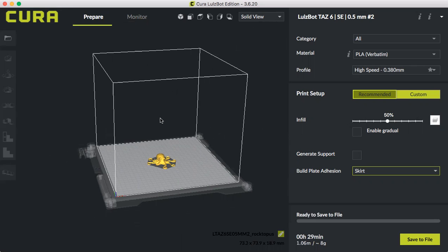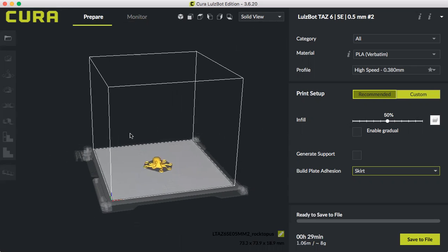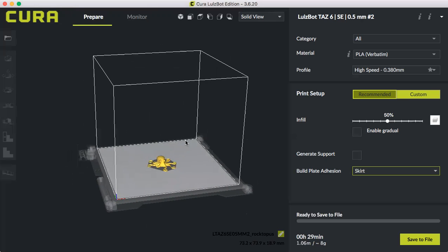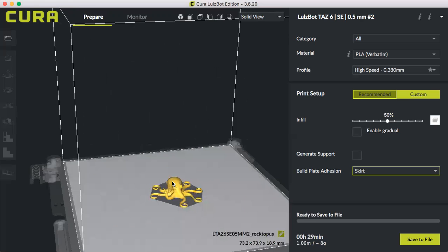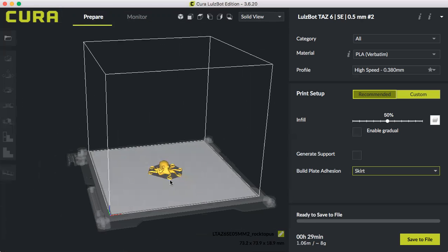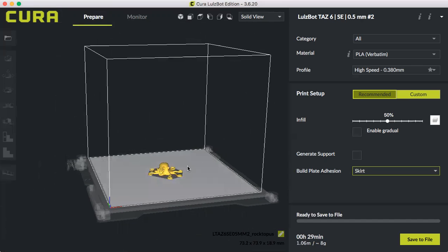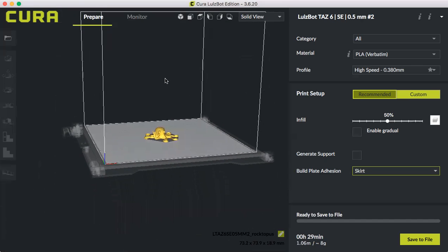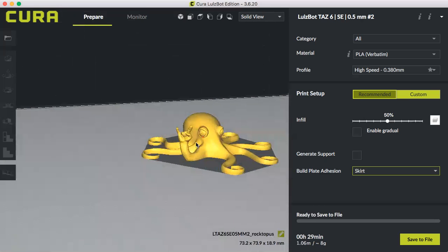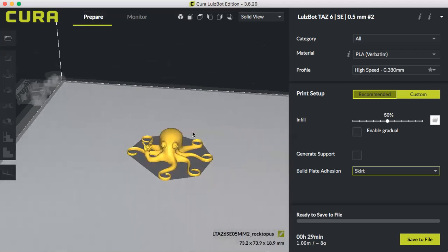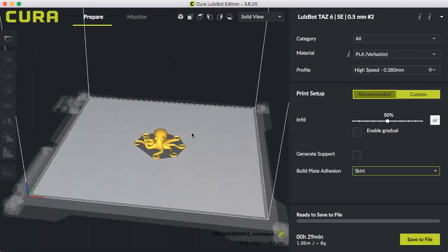If you push down your mouse button and hold it, it's going to pan. So you can pan with your window right there. Rolling the mouse button in and out is going to zoom in and out. And then holding down your right mouse button is going to allow you to rotate. The pan is going to come in really handy because when you zoom in, you might need to use the pan to get exactly where you need it to be. So holding down the mouse wheel will get you to pan.